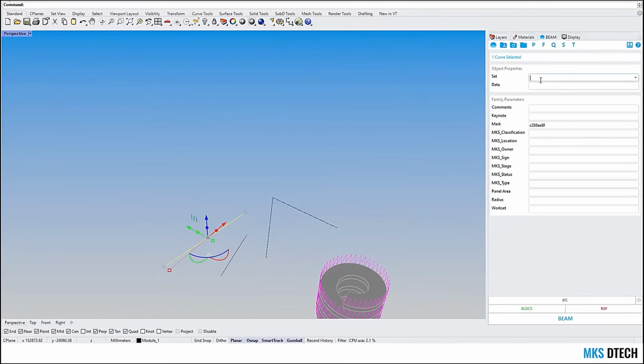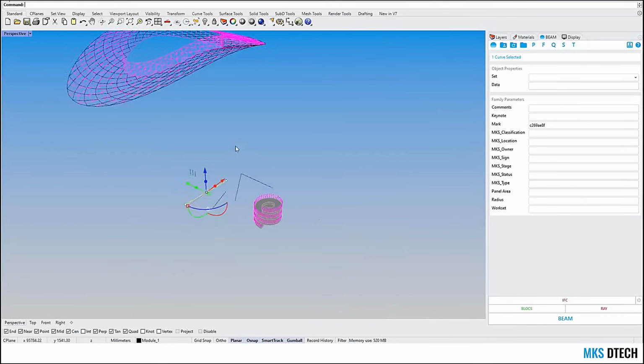It's really important to see this difference, because we are differentiating between solid objects that can be imported as solid geometry into Revit, and lines. We cannot import lines with BIM. But what we can do is apply adaptive components or send these lines to Dynamo for a more complex workflow.